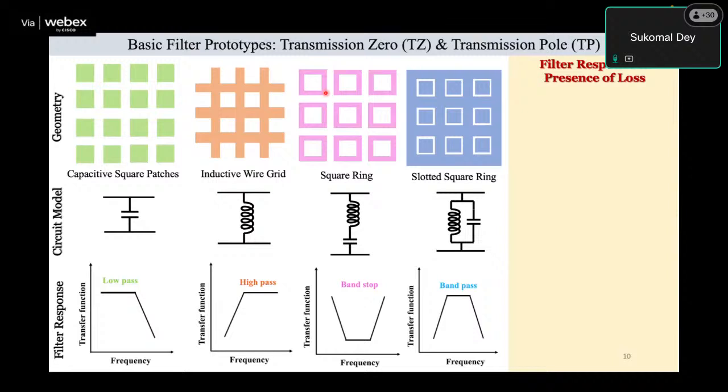What does the Floquet port do? It considers your array, whatever you are showing as one unit cell, as an infinite array towards the x and y directions. I told you all these are 2D-based FSS structures. So it would consider an infinite by infinite array of elements and simulate based on that. Ultimately, your job is to make your unit cell give your desired response.